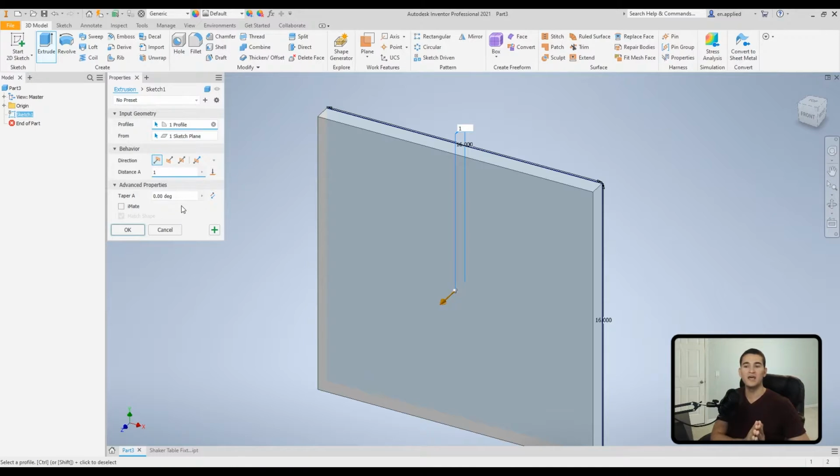mold, because if your molded part is a little bit too deep, you could have some issues with sticking to the mold itself. So a way to alleviate that is creating a very shallow taper towards the end of the part so that once the ejector pins start pushing off of the part, when the mold opens up, it helps the part release from the mold itself, and you don't get any sort of sticking or any damage to your molded part.